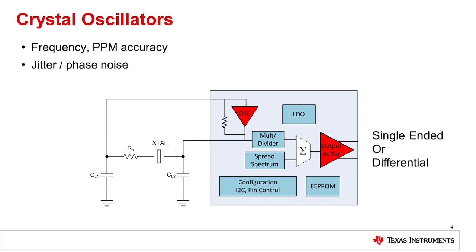Different flavors of reference oscillators infer accuracy and stability. The TCXO is temperature compensated to have a low ppm across an extended temperature range. The OCXO includes an oven or heater to maintain a temperature and have even lower ppm across temperature. You can also add a voltage control to adjust the load capacitance and frequency in a VCXO or VCTCXO.